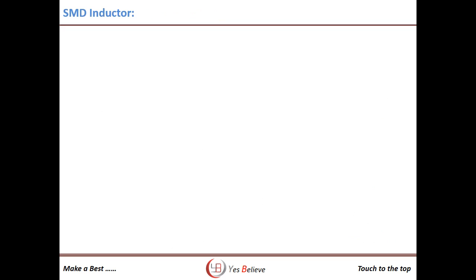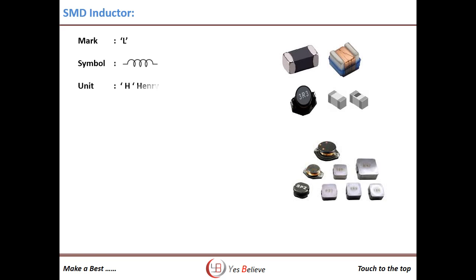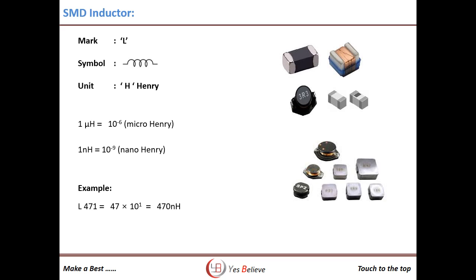The next component is the inductor. Due to the small dimension of SMDs, the SMD inductors are available in limited values of less than about 1 millihenry. It is a metal conductor looped through a ferrite bead with end caps. They are dark gray in color. Larger inductors and transformers may be through-hole mounted on the same board.